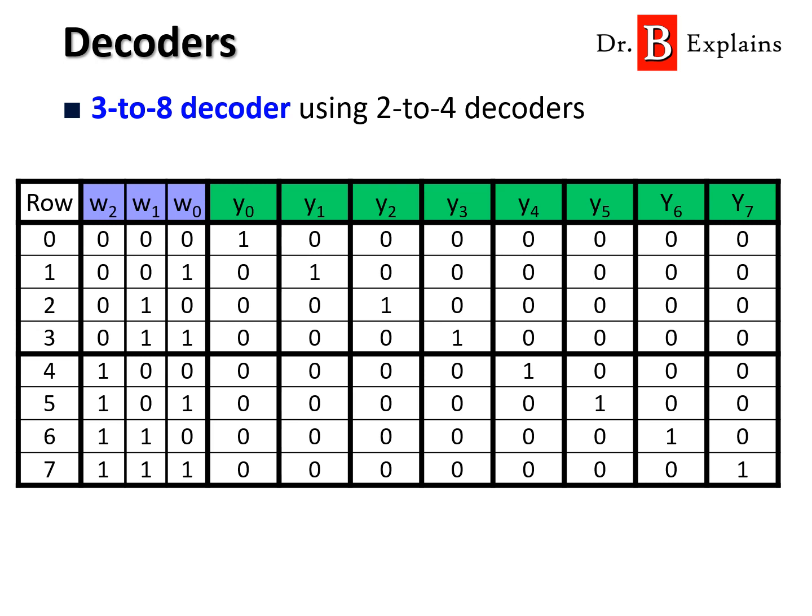So first we're going to use only 2 to 4 decoders, and you have to think about how the 2 to 4 decoder works. Depending on the value of the input to the decoder, that's the output that is going to be high, or on, or active. In the case of the 2 to 4, we need to select two inputs.